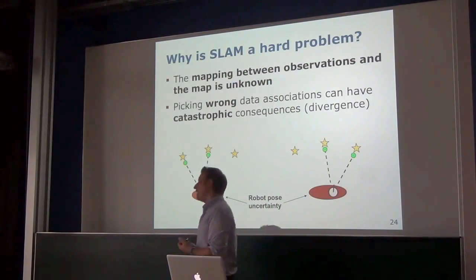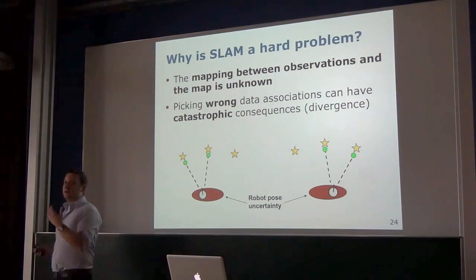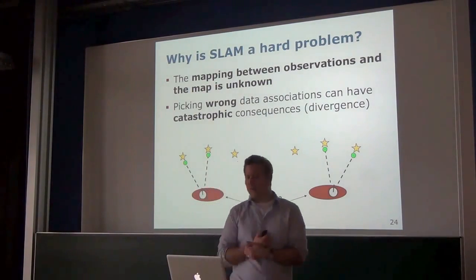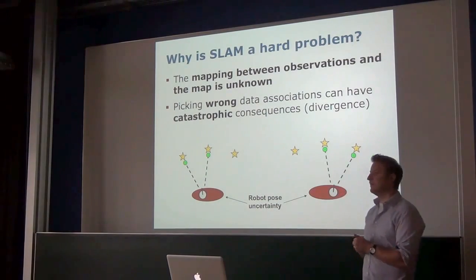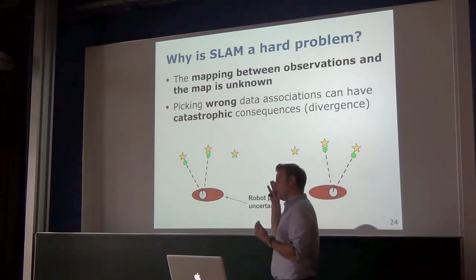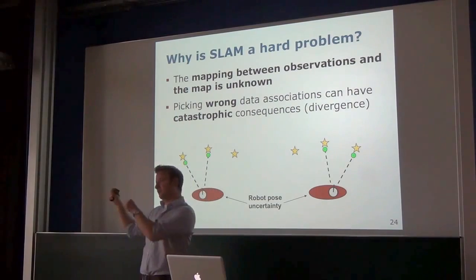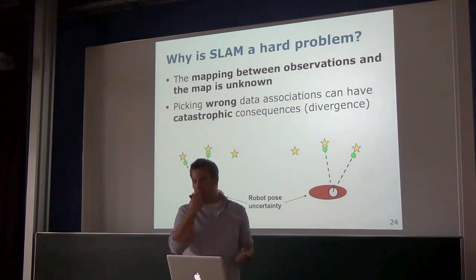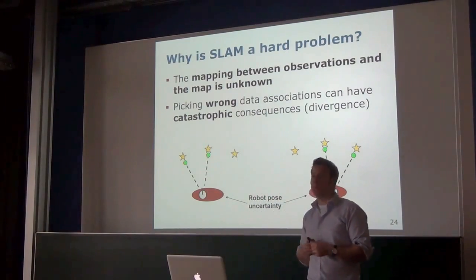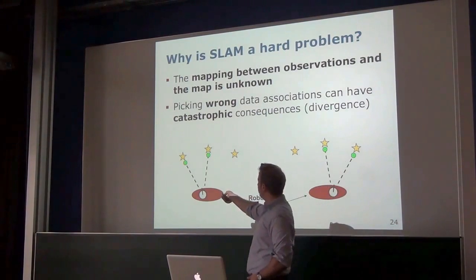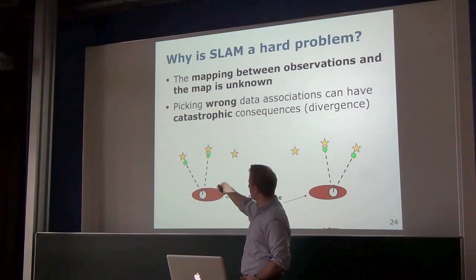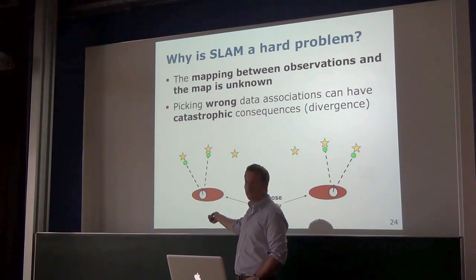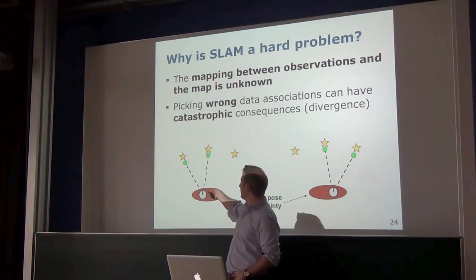Okay. Second thing, why SLAM is a non-trivial problem, and this is because of what I said before: data association. Data association is the fact that, given I have observations, I do not know, for example, if I observe features, to which features in my environment model these observations correspond. So for example, if I have 3 landmarks located like this in my environment model, according to the uncertainty I have about the robot's pose, and the robot observes 2 landmarks.